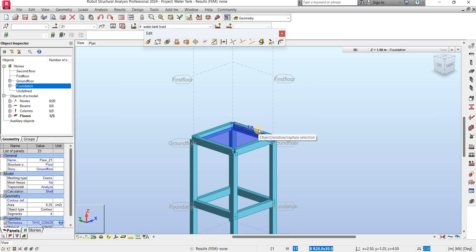Now we work with kilonewtons. Converting to kilonewtons will be 49.05 kilonewtons. Now we have to convert this kilonewton to kilonewton per meter square. That's where the surface area of the slab comes in. The surface area is assumed to be 2.5 by 2.5, which is approximately 6.25. So I'll approximate my surface area for this slab to be 6 meters.